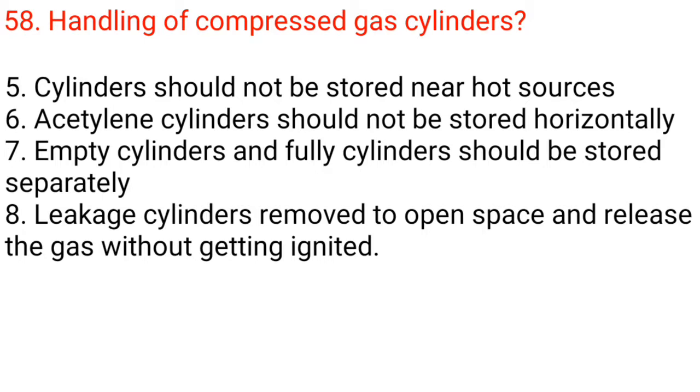Cylinders should not be stored near heat sources. 6. Acetylene cylinders should not be stored horizontally. 7. Empty cylinders and full cylinders should be stored separately. 8. Leaking cylinders should be removed to an open space and the gas released without getting ignited.